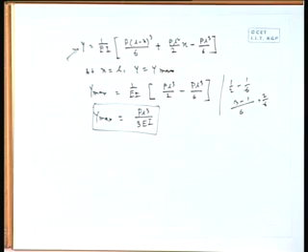Sometimes we get confused whether it is L square or L cube or L to the power 4. That form is there all the time. You will find EI below, here PL, the unit you can always check. So EI means E will be in SI unit Newton per meter square, and I will be meter to the power 4. So below it will be Newton meter square. Here P will be Newton, it will cancel. So Newton meter square means it will be L cube. So meter cube by meter square, it will be meter.